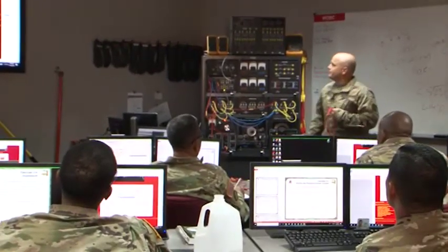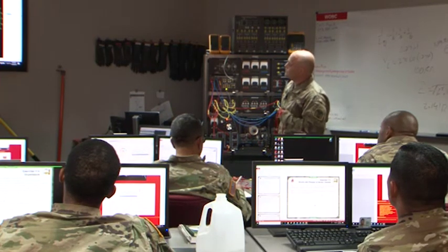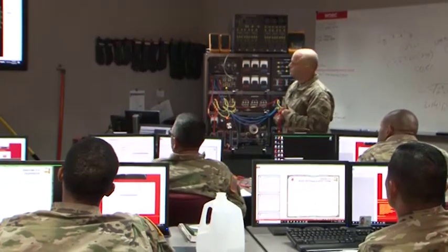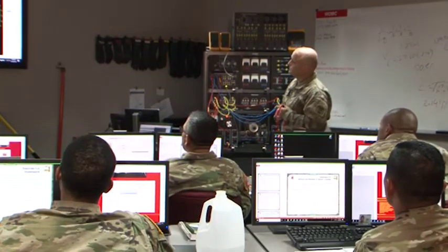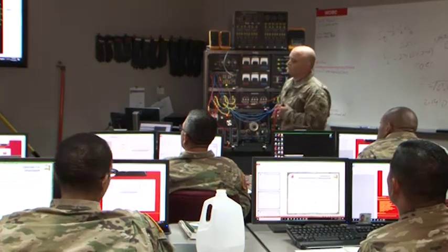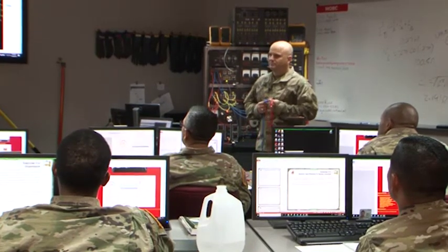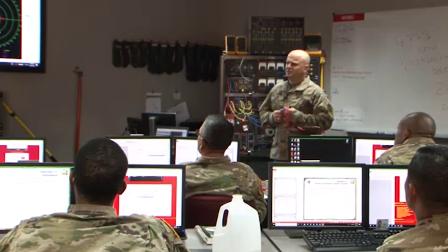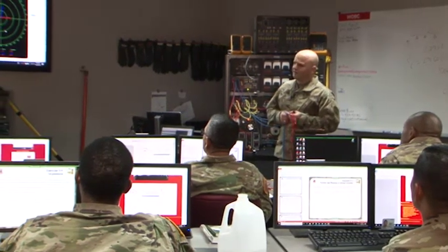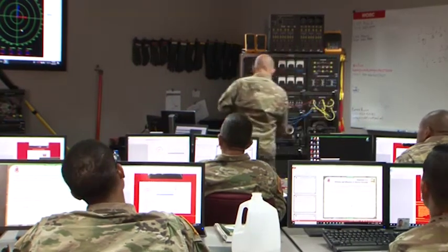Let's take a look there. I see E1 and I see E2. And what are those each reading? 85. They're reading 80, 85? So that's a series circuit, so those voltage drops should sum up. That's Kirchhoff's voltage law. They should sum to the source. Does that mean our source should be 160 in this case, or 165? Should it? Hmm.